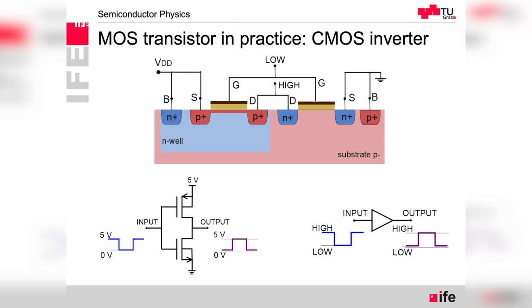So operating conditions: the power supply level might change, there might be some noise on the power supply, and we want it to be independent of the noise. And also there are temperature variations, and we have seen that the threshold voltage, for example, is highly dependent on the temperature. Because of that, the characteristics will also change with temperature. Also, the charge transport properties depend on the temperature. So there are things to do behind the scenes, but that's the basic concept, the ring oscillator.